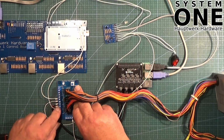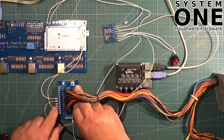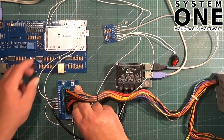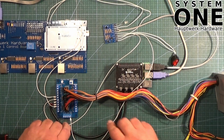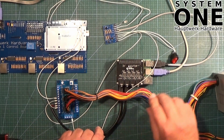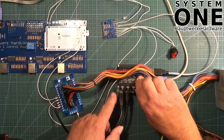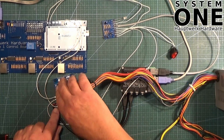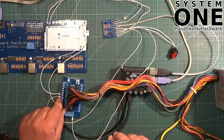So we are only using plus 5 volts and ground here. That's what these connections are. So there's a plus 5 volts and ground going to our control board. There is a little, I guess you'd call it a little USB-C pigtail thing. So if we move those out of the way, that's powering the Raspberry Pi. We've got a little USB-C connector here that comes round, and that's just 5 volts and ground connected to the power supply here.